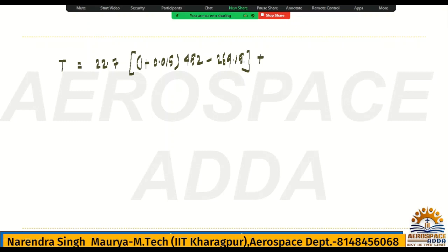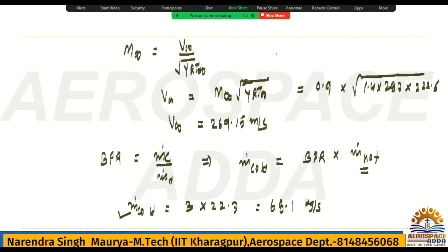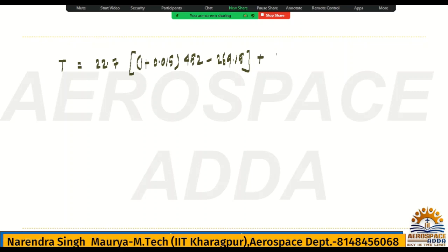What is the pressure thrust for the hot? So PEH. See PEH. What is the value of PEH? 32.56, right? It is given in kPa, na? So that we need to take care. Okay, we do not have to commit mistakes. 32.56 kPa they have given to us, so that unit should be perfect, otherwise you will suffer, na?